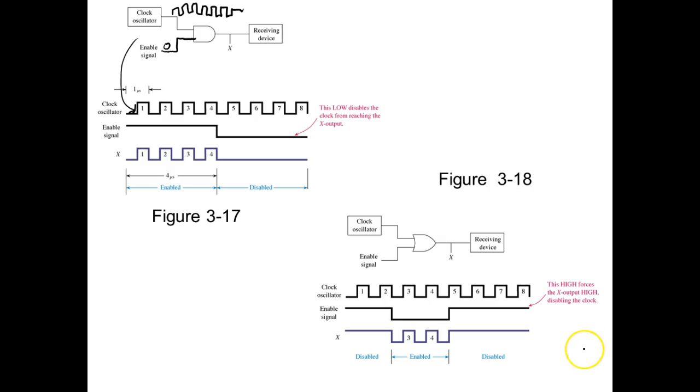So what happens if I don't put this input right here to a 0? If I just leave a nothing there, then this gate is going to do something weird because I'm putting an illegal something out there, right? Does that make sense? So when we say we're going to put a 0, or a 1, or a high or a low, either one of those would work in this class. But a nothing to digital is weird. We don't ever want a nothing.